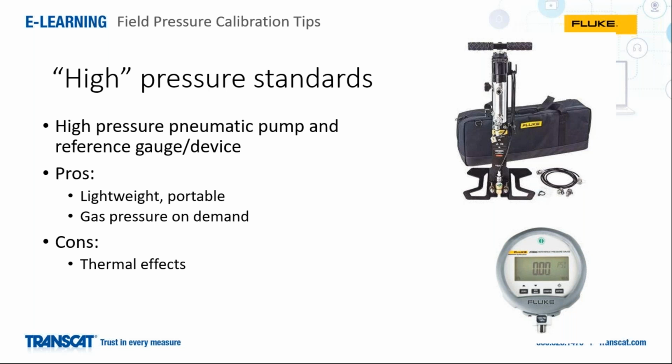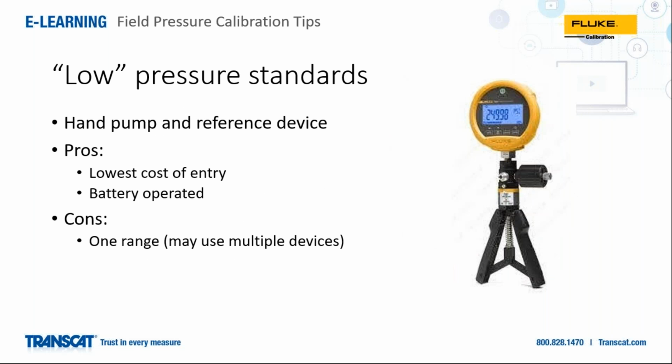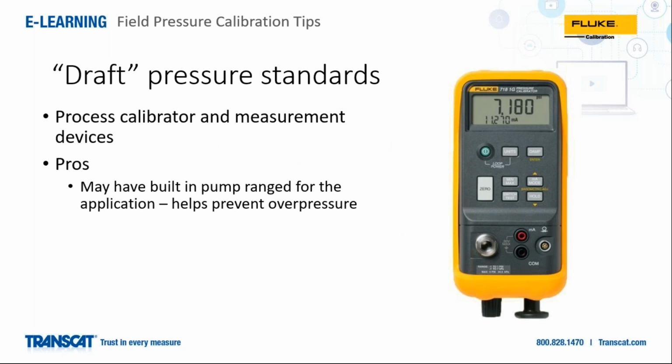All right. Are the different size pumps interchangeable on the 718 or 719? Could you replace a 300 psi pump with a 1 psi pump? You can, but there are some other technical differences. So in one of my previous roles here at Fluke, I got into some of the internals of the process calibrators, and there are some construction differences besides just the pump.